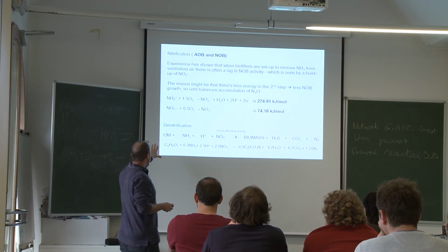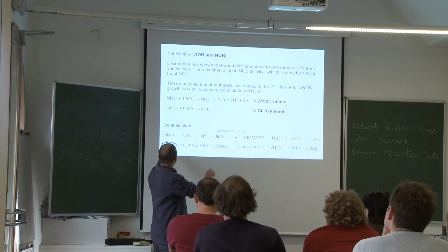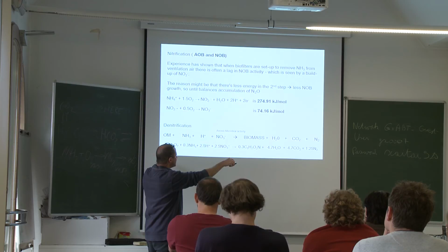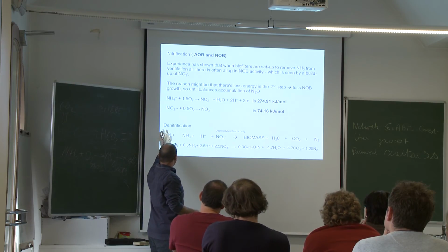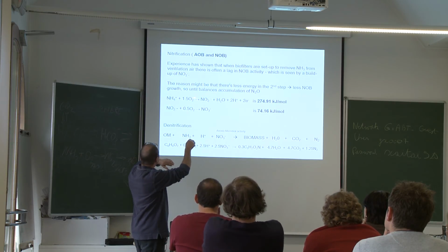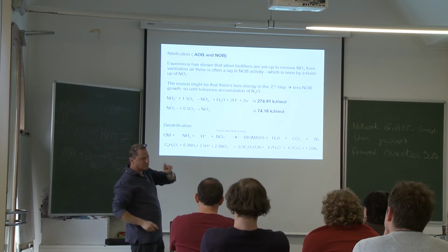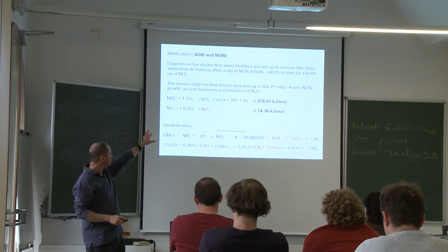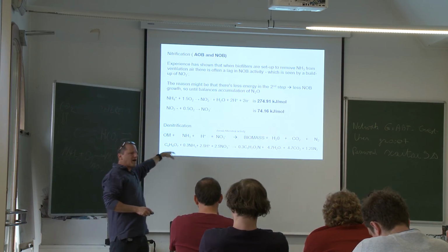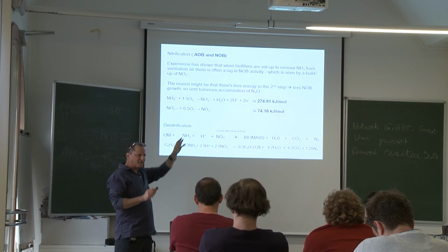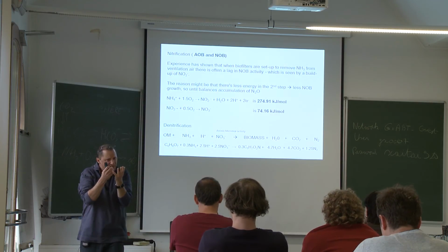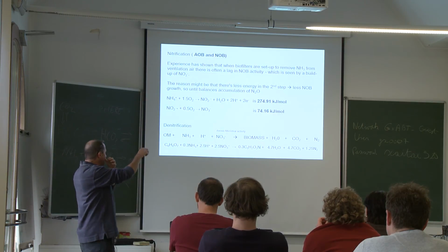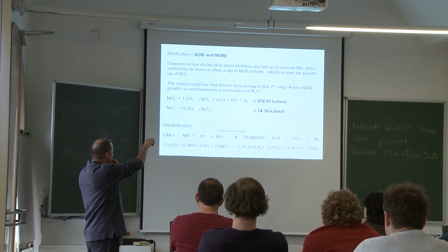And denitrification, removal of nitrogen, is basically taking this nitrate and converting it into N2 gas, which is inert. These bacteria need carbon dioxide. They're autotrophs. They're slow growers. That's very important to remember, because they're often outcompeted by other bacteria, specifically in systems that have a lot of organic matter in them. So we have to make sure that we maintain the right conditions for these as well.